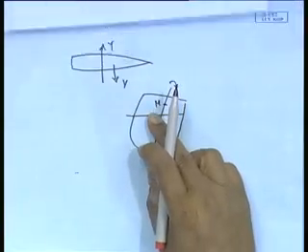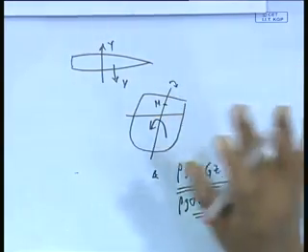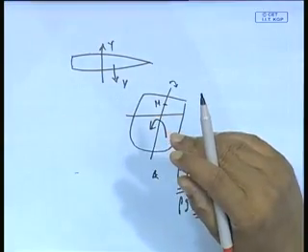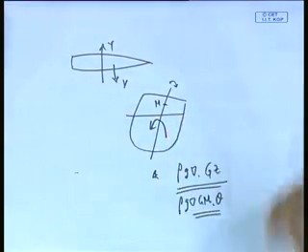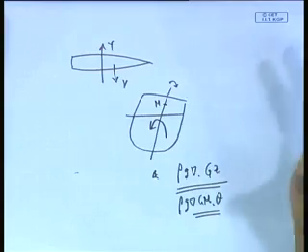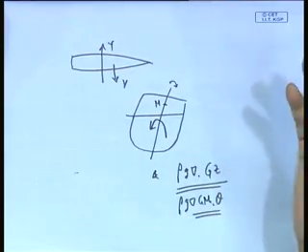If I give an external heeling moment, a wind, I get a theta created, a heeling angle created. I remove the external force, and the moment generated in the hull because of hydrostatic pressure tries to make theta smaller and smaller, eventually 0, or tries to make theta bigger and bigger.